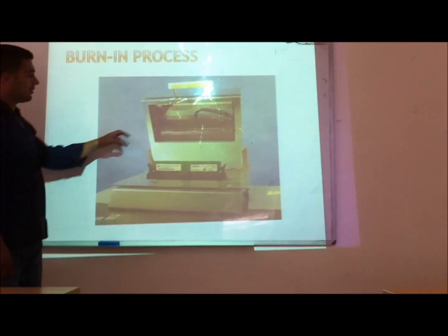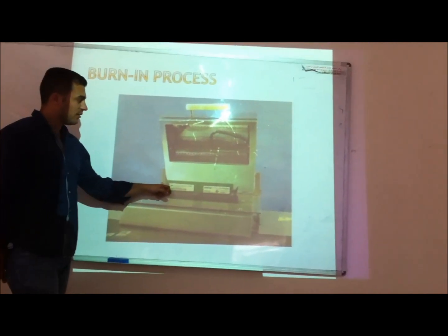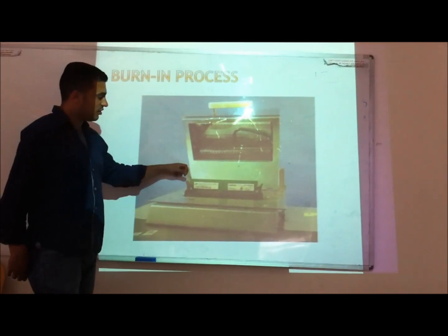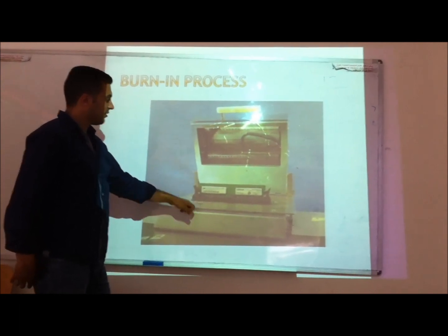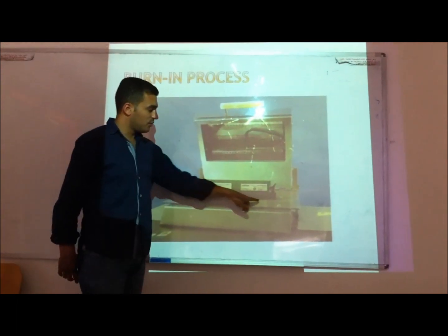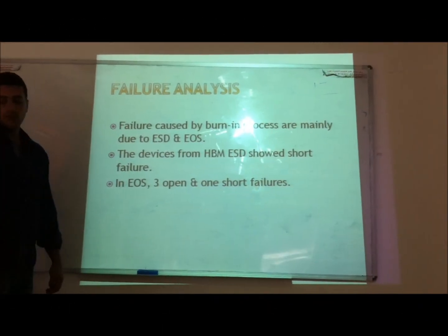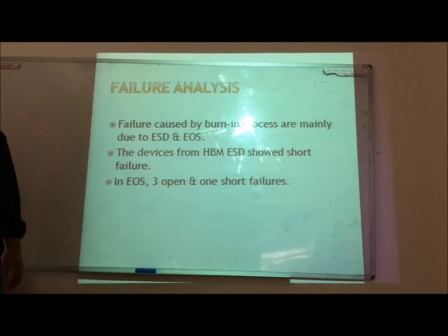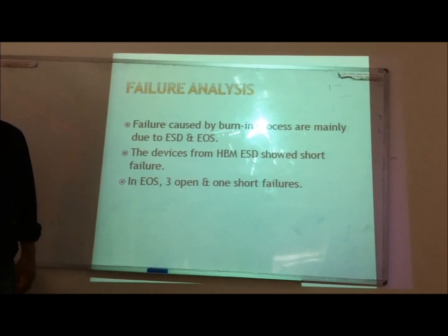For example, this is the burn-in process. We have a round computer component put in this chamber. This chamber has a very high temperature, and when it is tested, this door is closed for a specific period of time. After that, we accelerate the conditions for this. Failures caused by the burn-in process are mainly due to ESD and EOS damages.